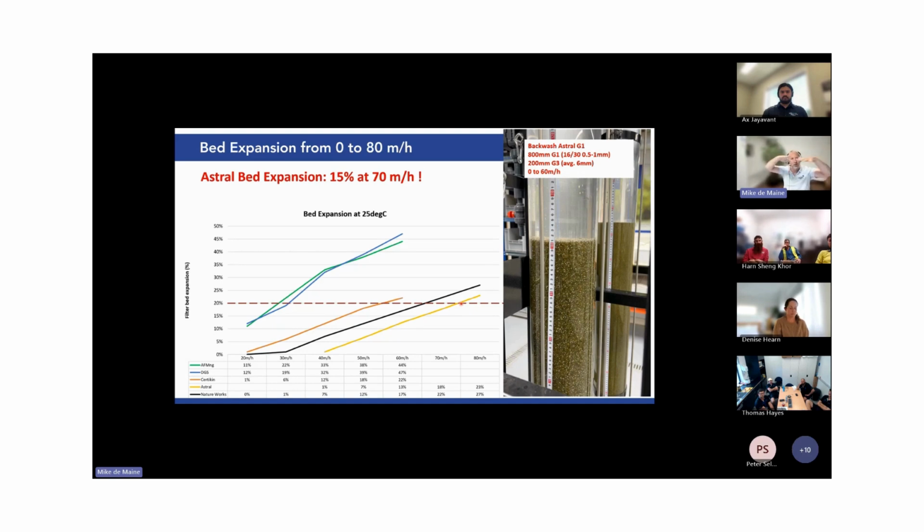They go up into the water column, they don't really release, and then every time you come back into filtration mode, over time, your pressure differential increases. That's straight away an indication that your organics are heavier than what your backwash velocity currently is. So you should increase your backwash velocity. Our general experience is 40 meters per hour will release all organics.